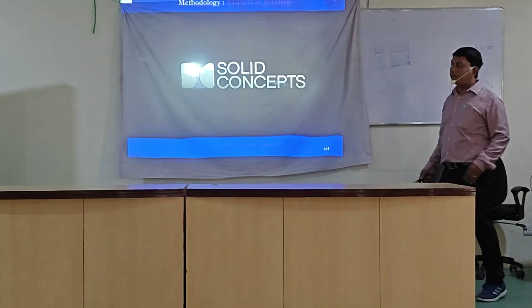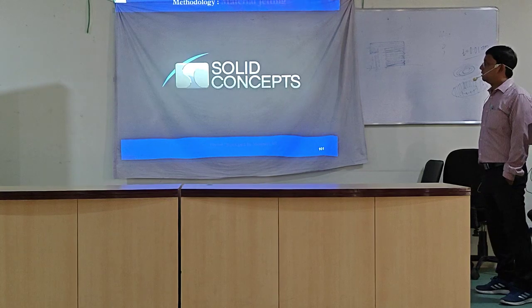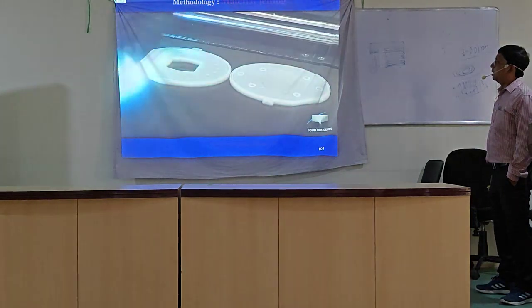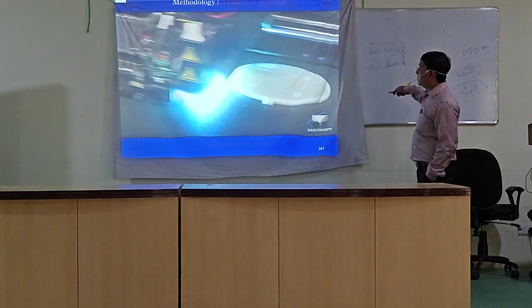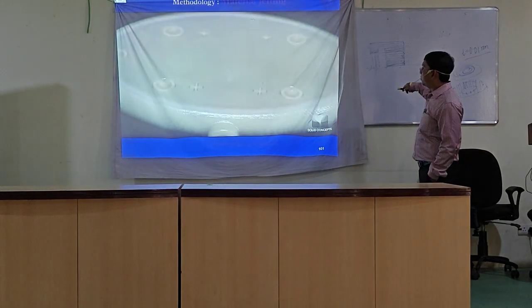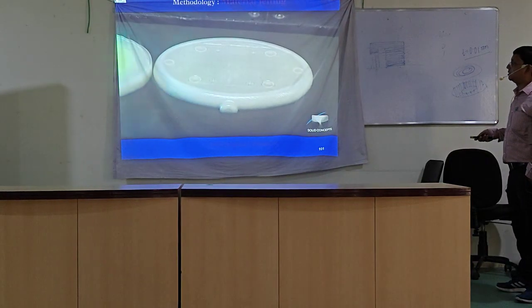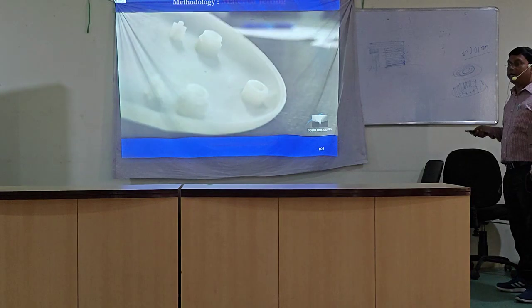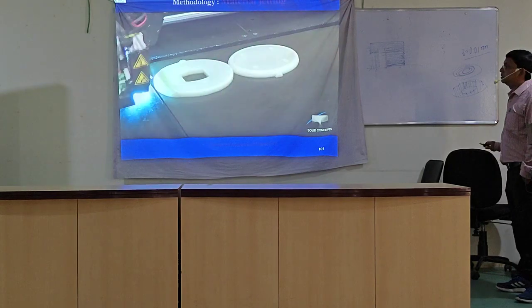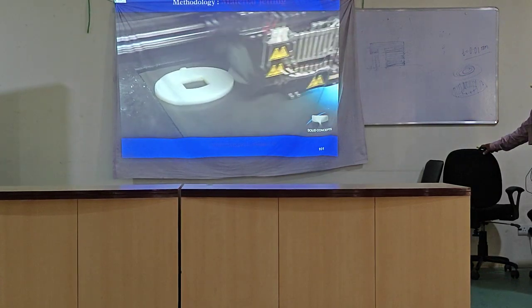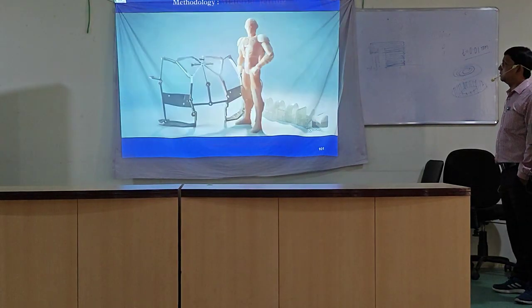But very precise components you can manufacture with reasonable accuracy. This is the PolyJet. You see this, this is the UV ray. Before that there is a dispensing unit. It is a faster process than SLA. PolyJet is one of the fastest prototyping processes available to develop high-precision physical parts, and is ideal for smaller parts, custom jigs, and fast patterns.